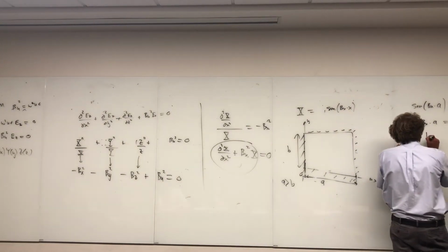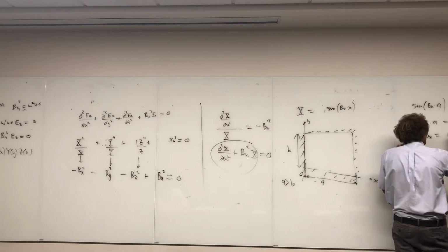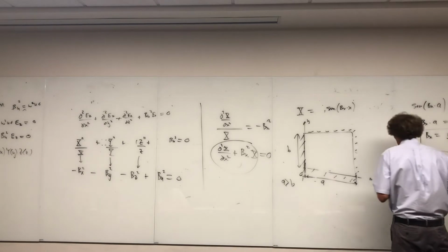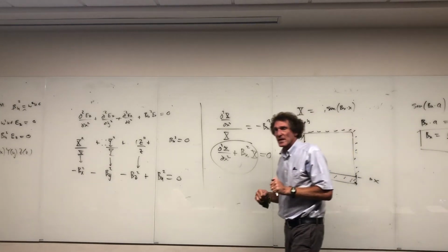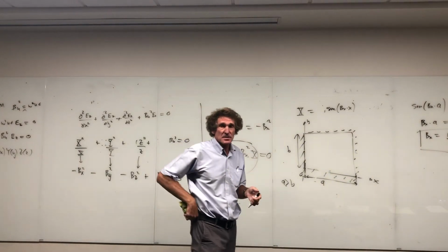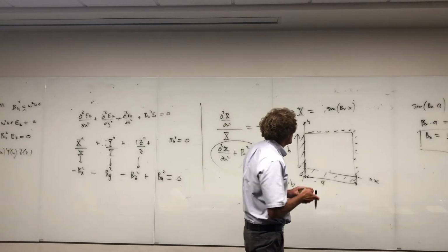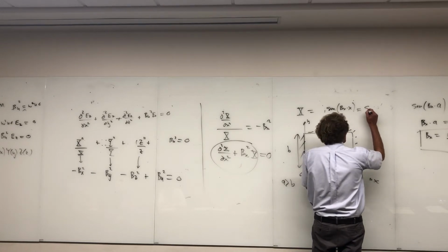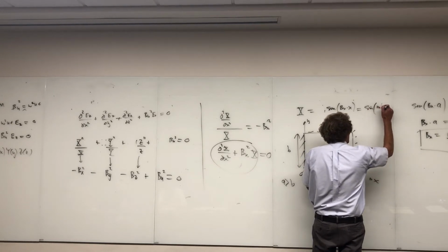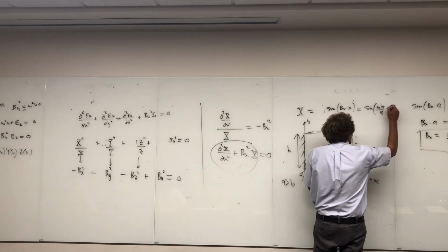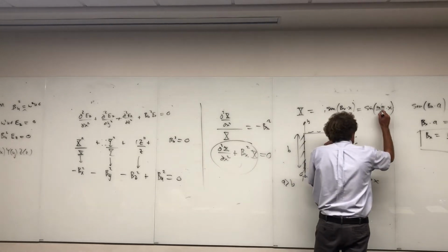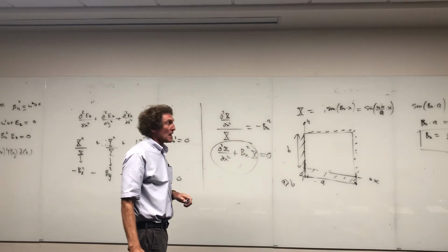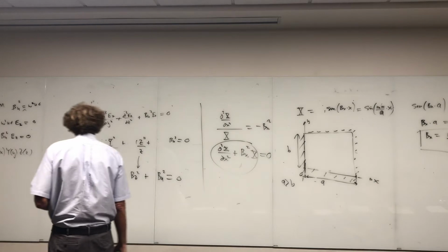That means really beta x here is equal to m pi over a. He likes m as an integer for that one, and it's normally m for the horizontal axis. It's just the standard. So that's what beta x is. In general, then we can write the solution is simply going to be equal to the sine of m pi over a times x. Now we figured out even when beta is in there, what beta x values are. Got me, class?